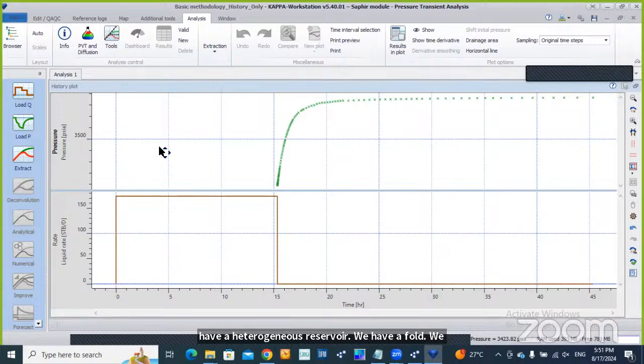And from your deep understanding of your reservoir and your production performance as wells, you can determine, yes, we have a strong aquifer pressure support, or we don't have a strong aquifer, and you have other tools like PDT and so on. So you can determine the signature or the behavior of your reservoir and implement this in your well test analysis. So this is simply the first step, as I mentioned.